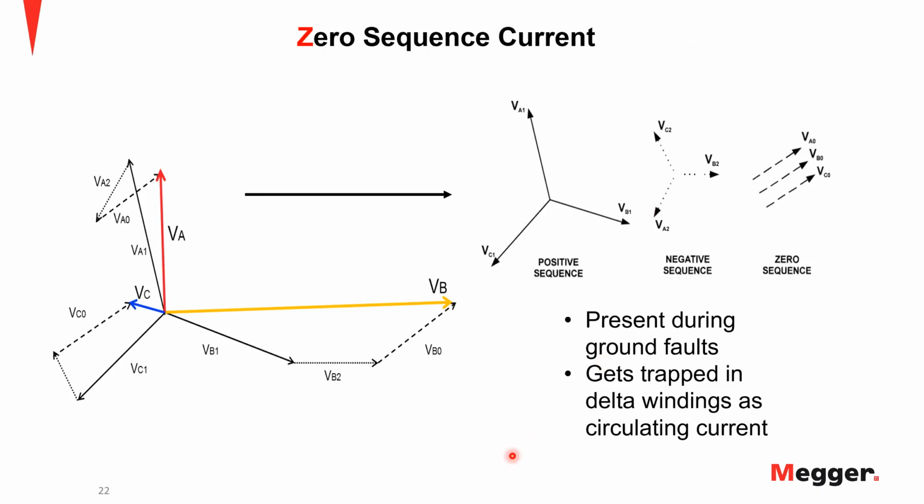So the next challenge is the zero sequence currents. Zero sequence currents are present in the power system when we have an unbalanced fault. Like here is an example of an unbalanced fault, and any unbalanced fault can be resolved into 3 balanced vectors: positive sequence, negative sequence, and zero sequence components. Now, using the symmetrical components, it's always helpful to analyze unbalanced faults. Today, I will not be talking too much about the symmetrical components. Rather, I'll be only focusing on the zero sequence current.